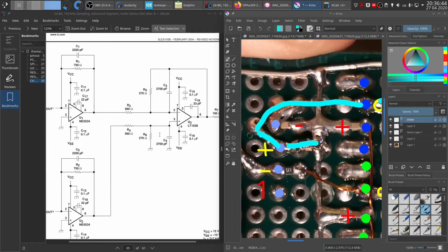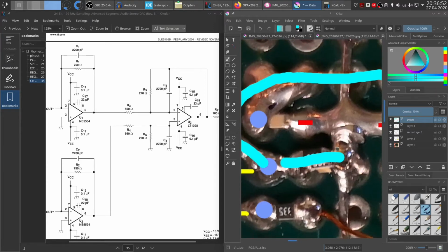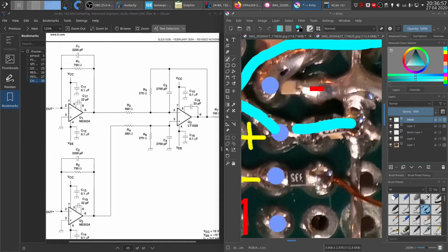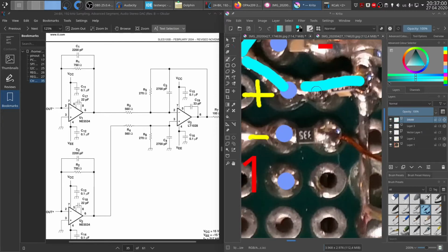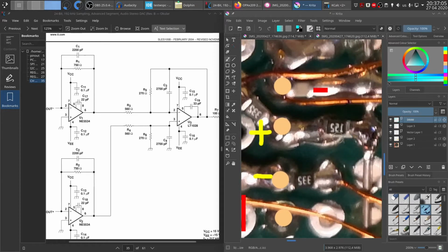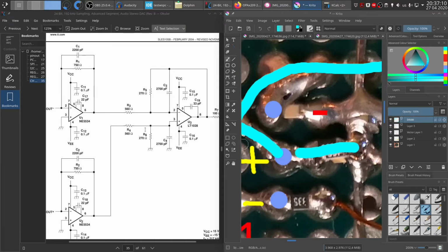Also you can see there's a capacitor on the bottom of these two resistors, and this is this 2.7 nanofarad capacitor over here. And in this case there's also one on the bottom of this resistor. Also you might have seen, maybe let's go to the bottom one, that I used, it doesn't seem very good, but I used two parallel resistors because I didn't have a 270 ohms one, so I used double the size of the 270, which is 540, and I just put them in parallel and I got the same result.